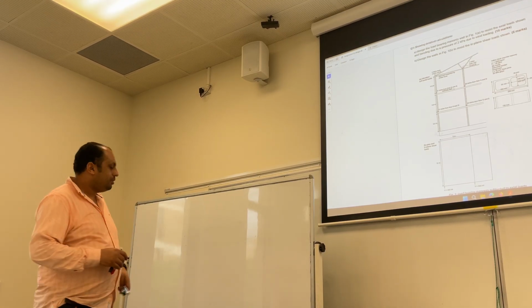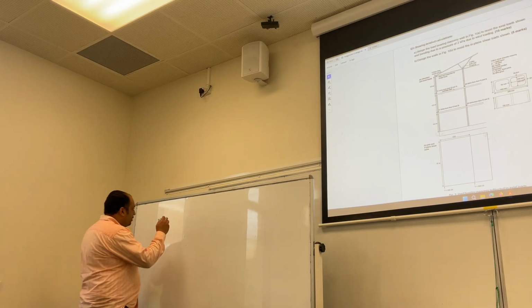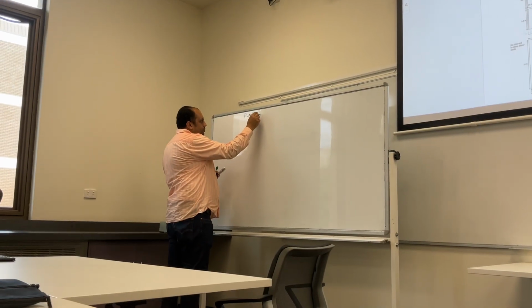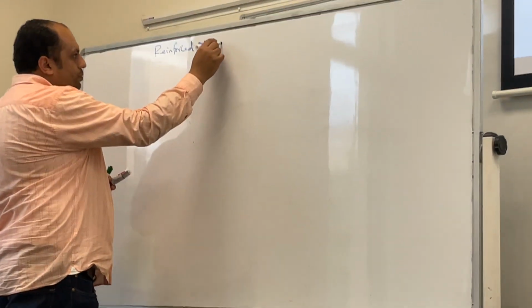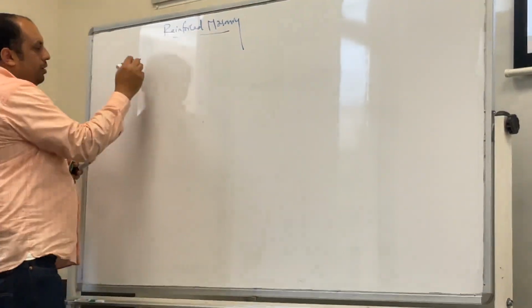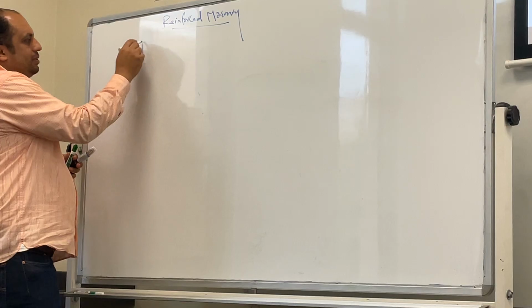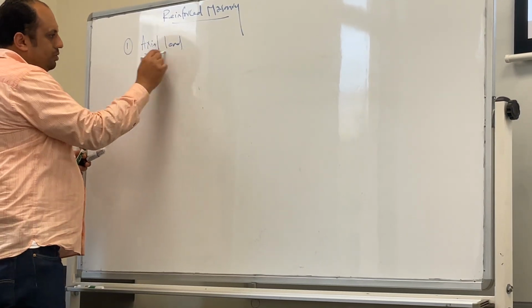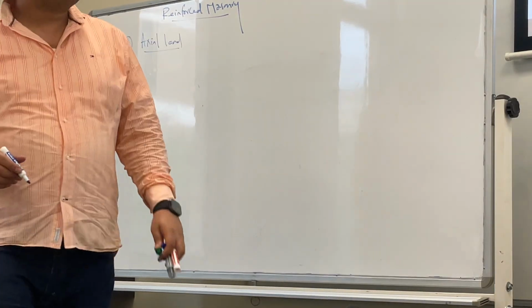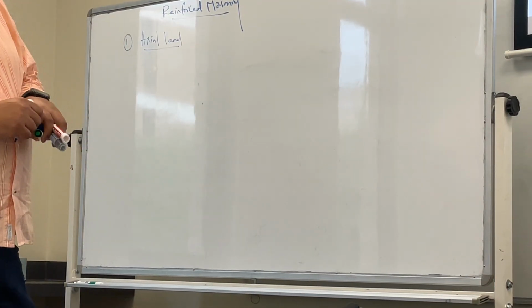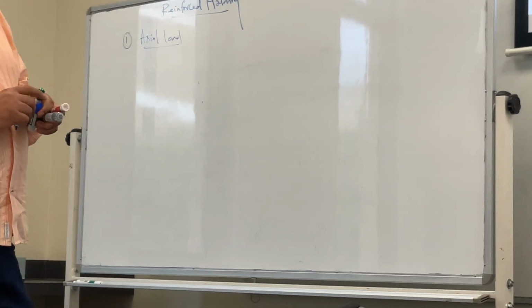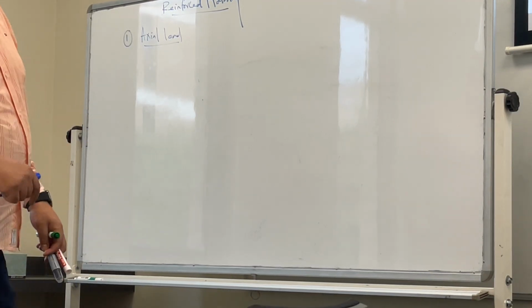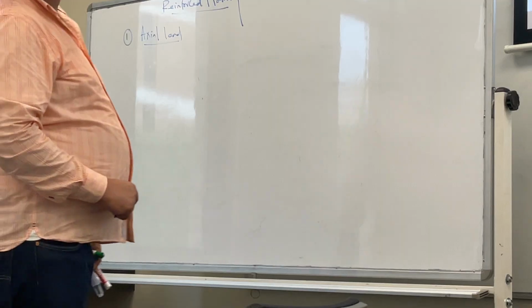Okay, so one week for the reinforced masonry assignments. The first requirement is design for axial load. Design the load-bearing masonry wall to resist the axial load shown and bending due to the pressure of 2 kPa. So what is the maximum axial load here?